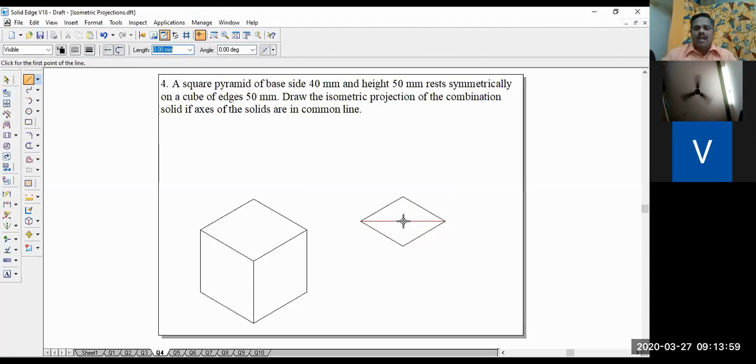From that, I have to raise the axis height now. So I will take this midpoint and raise the axis height. I'll take the axial line only, axial line 0.25 mm thickness. So the axis height is here 50 mm. I'll choose the axis height as 50 mm, angle 90 degree. So this is the apex now. Apex has been drawn, right?